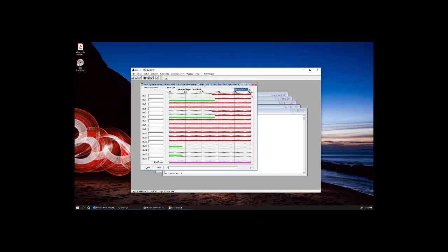Now the way this works is, here's when the monitor tripped, and then it shows you 30 seconds before the trip. So there's 6 seconds, here's 11 seconds, 17 seconds, 20 seconds, and 30 seconds right there. So now we can just watch the intersection. It was running normal on 2 and 6 with the PEDs flashing on 13 and 15. We're getting there. Now we're getting to 15 seconds. Let's quick here. Get down to 2 seconds.